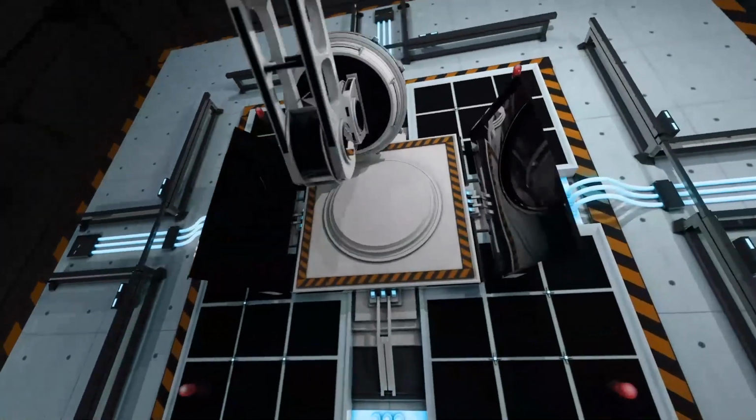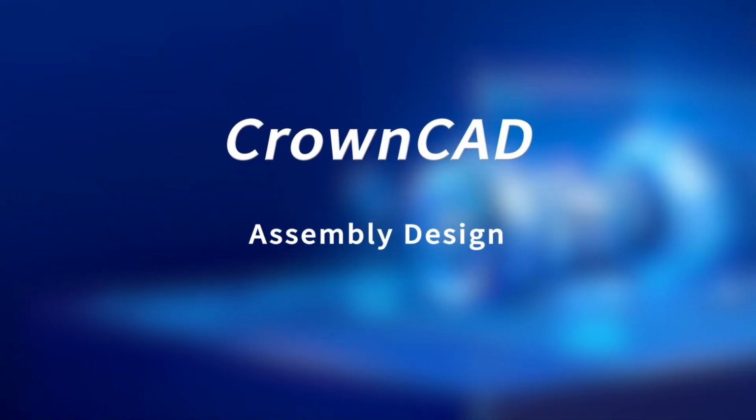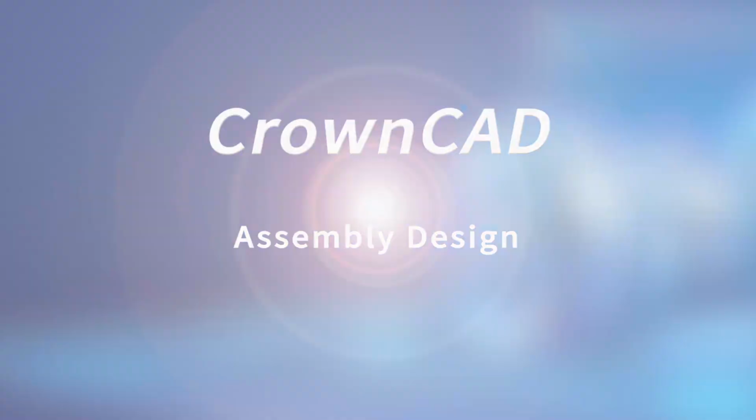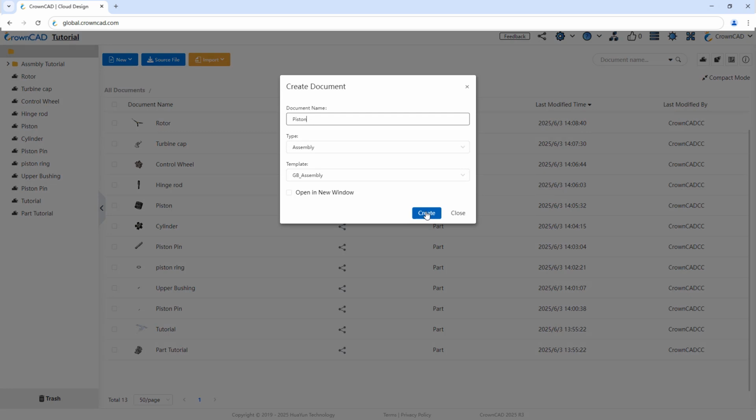Hi, I am CC. In this video, we'll guide you through the basics of CrownCAD assembly design using a radial engine example, helping you master the design workflow quickly. First, click on New and choose Assembly to create an assembly file.